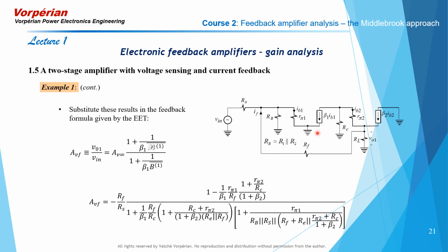So on the circuit diagram, we can quite clearly see why, when β1 is 0, the gain from input to output, which is an attenuation, is a positive number. And when β1 is very large, the amplifier is strong, and feedback action is taking place, the gain is inverting. It's essentially minus RF over RS. And that is what explains the presence of this negative sign here.